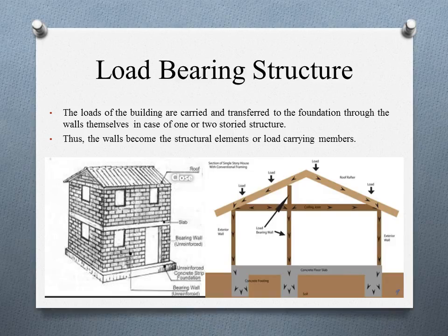When the wall will collapse in any situation, the whole structure will collapse. Load bearing structure is bad at earthquake resistance, as shock wave produce irregular tension and compression in columns. Tension is borne greatly by steel of RCC, which is absent in load bearing structure. Here you can't see any use of steel in this construction. Therefore, it cannot bear the tension.